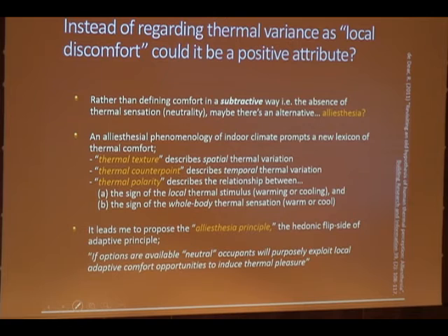So it leads me to propose an alliesthesial principle, which is in some ways the hedonic flip side of the adaptive principle. And that is that if options are available, neutral occupants will actually deliberately exploit local adaptive opportunities to induce thermal pleasure. That thermal neutral is not necessarily the desirable endpoint of the thermal comfort game.